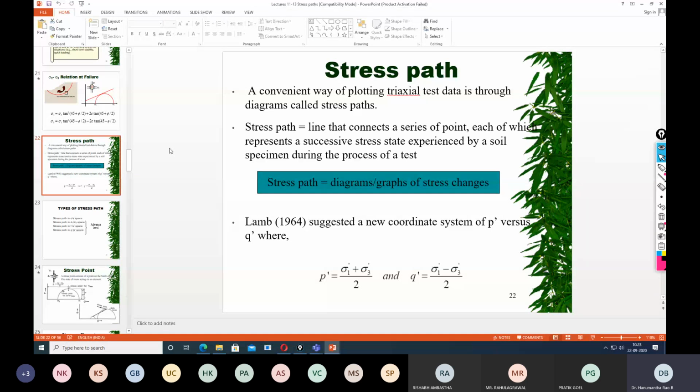So when the groundwater table is lowered, effective stress increases, and thereby there is a settlement. Once this process is entirely completed, you are again asking whether the process is reversible. That's what I explained. It is not reversible. No more settlement is possible, and therefore no more failure is possible.